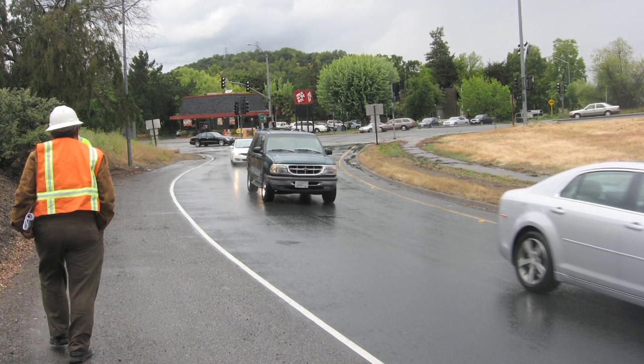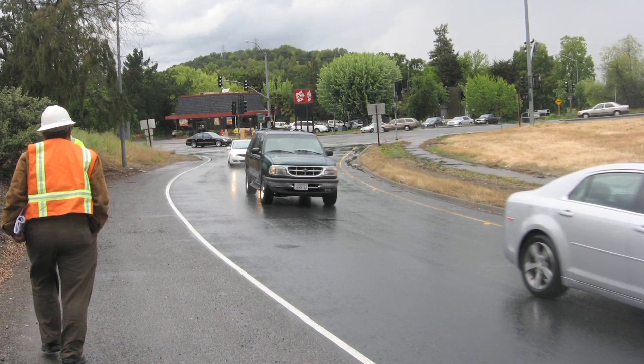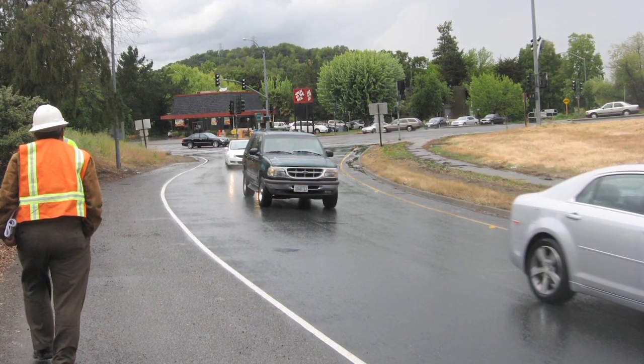And then the other thing too was just distinguishing the difference between want and need for this project. Traffic needs aren't always the same at every intersection, so whenever we had an issue with a certain intersection or area, we would look at the actual traffic volume for an intersection, for instance, and if the traffic volume didn't warrant it, then we could drop elements at this intersection. For instance, if there was a biological resource nearby, we would eliminate the widening if there wasn't enough traffic volume to allow for the widening or for us to have to widen.